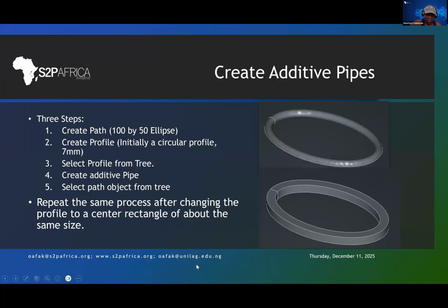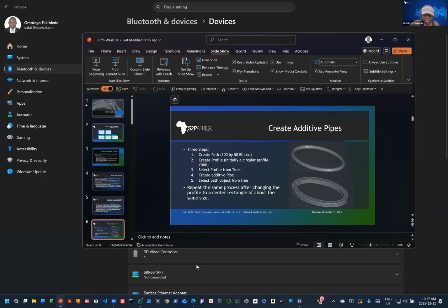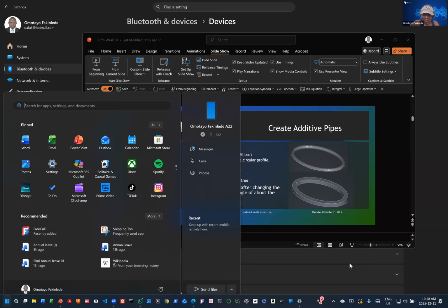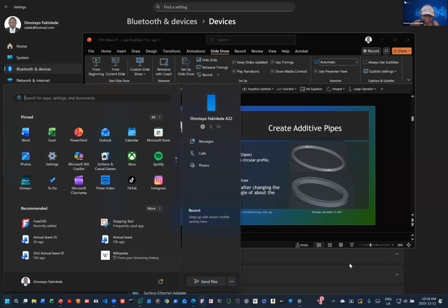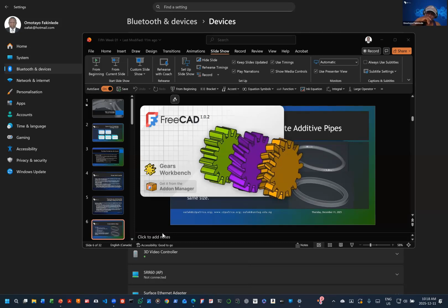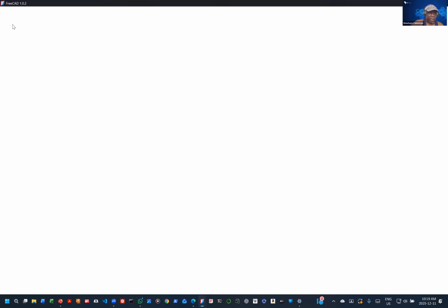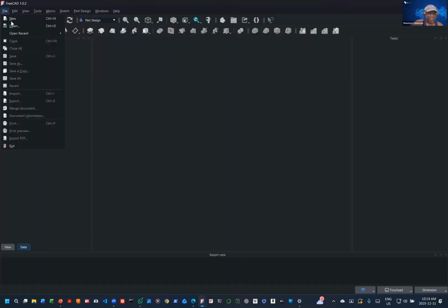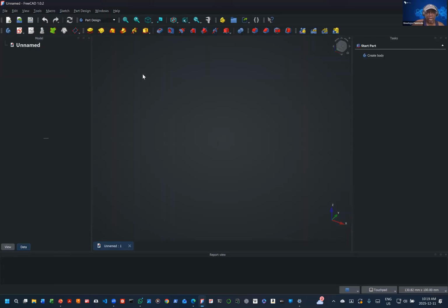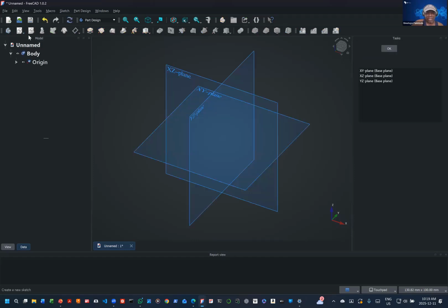But before we go on, let us just fire up FreeCAD and do a very simple sweep creation. So I want to do that now. I'm launching FreeCAD 1.0.2 for this purpose. Okay, so we can start a FreeCAD session with a new body, and we can start the sketching. Can start with the sketcher, and in this case, let us start a sketch on the XY plane.